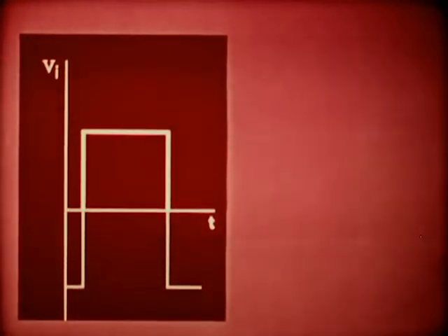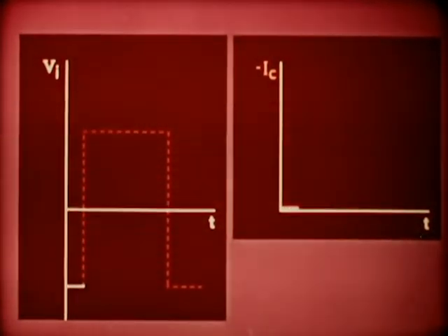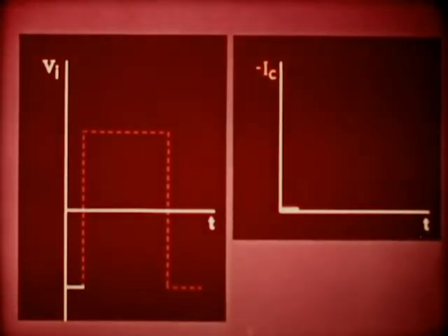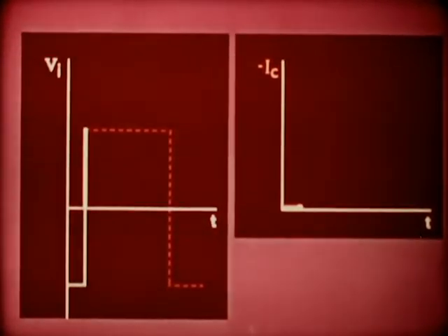Initially, because the transistor is at cutoff, the collector current is 0. Both junctions are reverse biased, and therefore the whole concentration curve is horizontal and of a very low value. What happens then when this high stepped voltage pulse is applied?